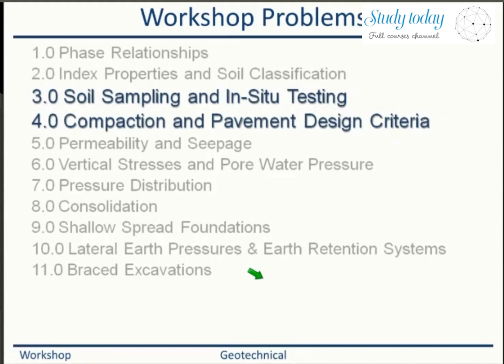I'm talking about high-rise buildings in New York. We have 60, 70, 80 story buildings, but these buildings are on rock. You studied RQD yesterday, so we're looking at the RQD and designing the bearing capacity for that kind of high-rise building with the deep foundation.